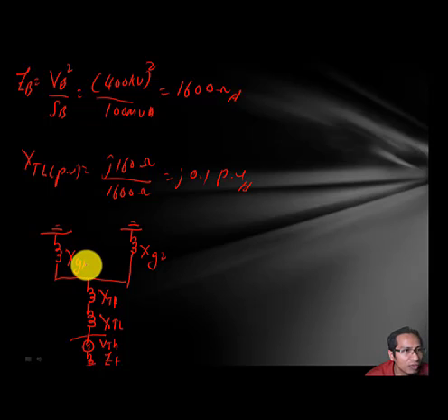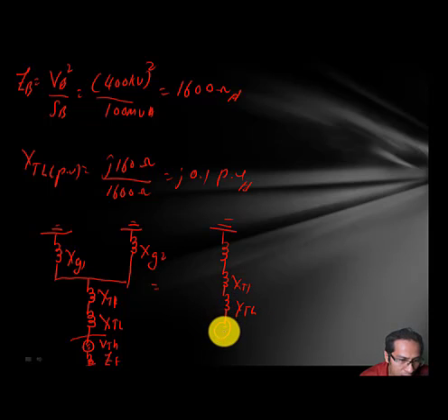So we have the values for XG1, XG2, XT1, XTL, and ZF. So this circuit can be simplified to become like this. Okay, we have XT1, this one XTL, minus plus VTH, and then Z fault. Okay, so this one is parallel between XG1 and XG2.